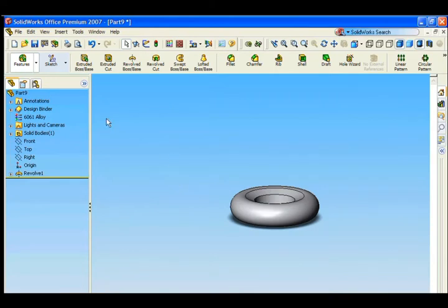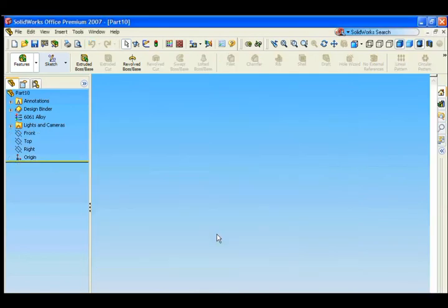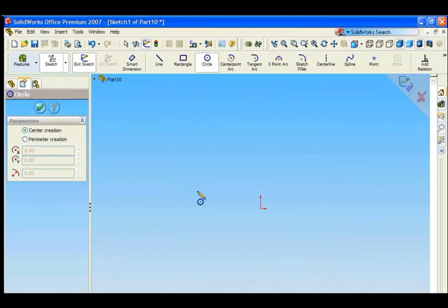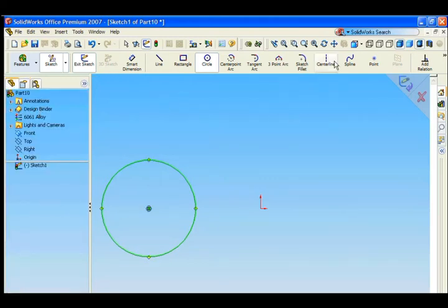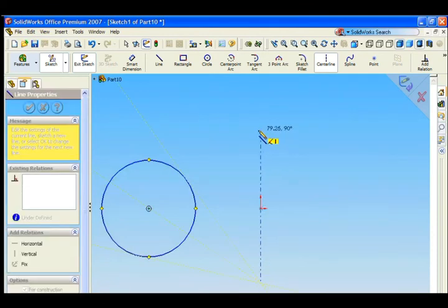Now, let's make a unique 90-degree corner bend. Let's click File, click New, click Part, click OK. Now let's sketch a circle on the front plane, and again, not on the origin, to the left of it. And let's make it 25 millimeters the radius. Click Enter, click OK, and let's draw the center line again in line with the origin all the way up.